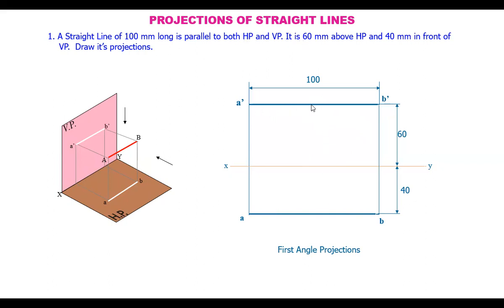In the front view, mark this line; this is the final projection of the line. Only the final projection should be highlighted. All the other lines should be thin. Show the dimensioning like this: the front view, the top view, and the actual length of the line.